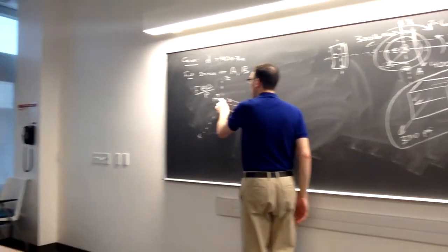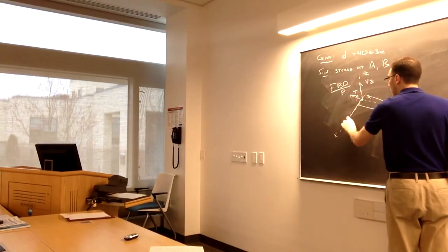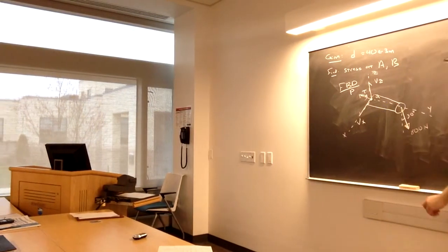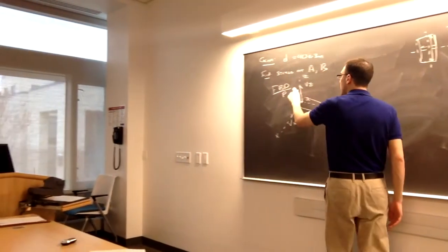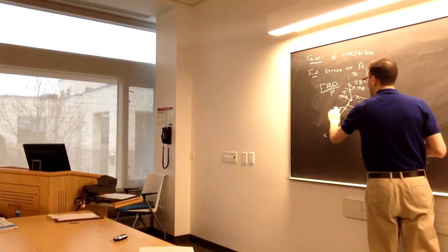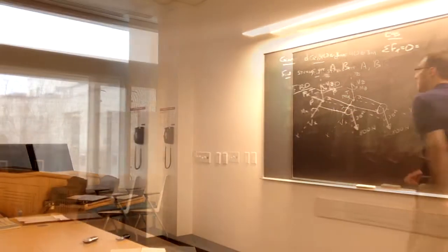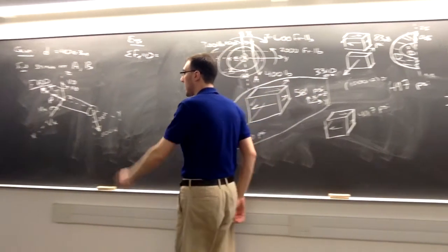So a component will be in the z direction, I'll call Vz, and a component in the x direction, Vx. And then like in the last one, I'll have a component of my bending moment around the z-axis and a component around the x-axis.